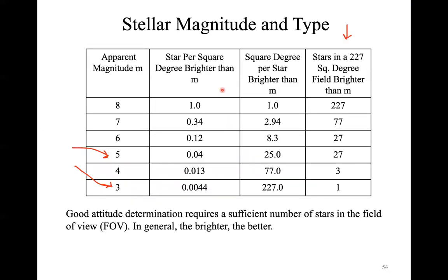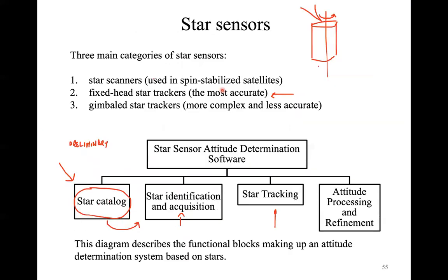But today, since we are going to conclude the star sensor part, we are going to introduce the gyroscope. You're going to see that between measurements of the attitude of the spacecraft from star trackers, you can indeed use the gyroscopes to determine the evolution of the attitude of the spacecraft between two observations.